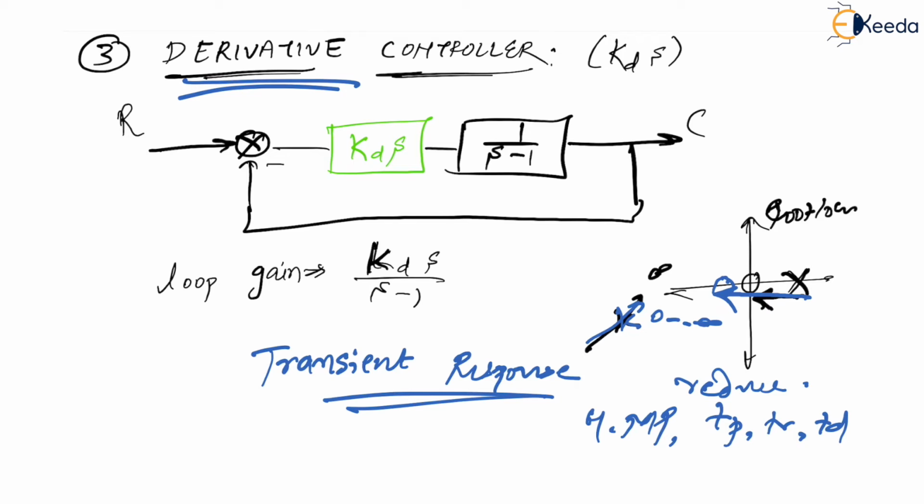Definitely first, second, and third. If you see first, second, and third, that is the proportional controller, then the integral controller, and the derivative controller. If you check out, this cannot be available in its ideal state. I mean to say, you can never have an ideal thing in practice. Ideally, you cannot have only a derivative controller. Hence, in practicalities, what we have is PI, we have PD, and we have PID.